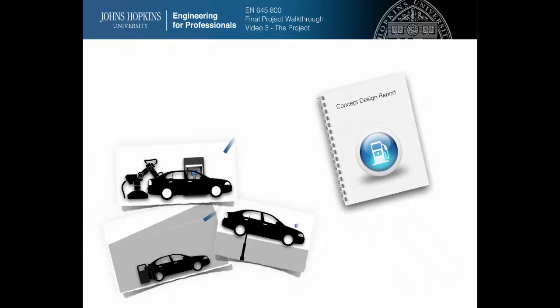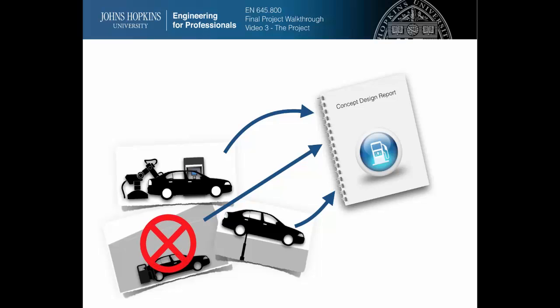I can do a little research and discover that some of these concepts are not feasible. For example, the heated garage may not be feasible since current federal gas station laws require refueling areas to be open to the atmosphere for ventilation and fire safety purposes.